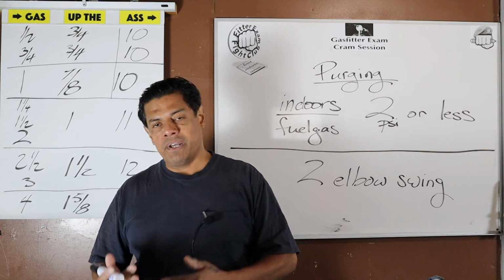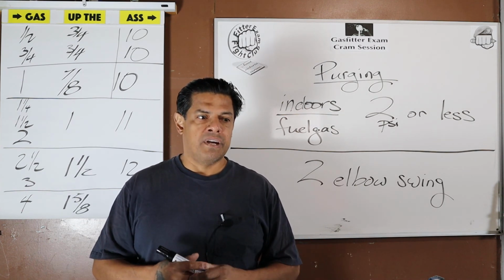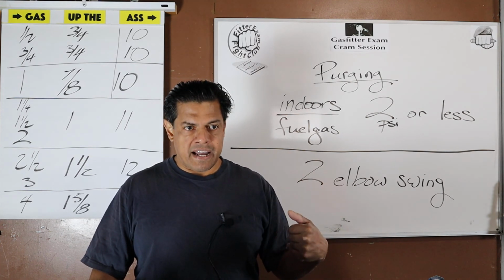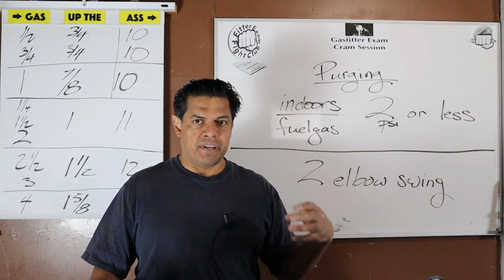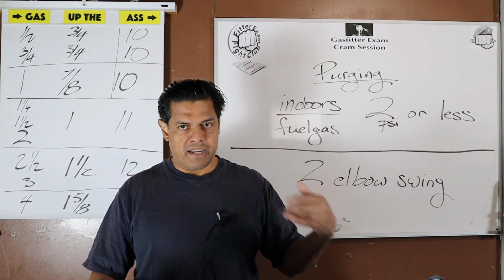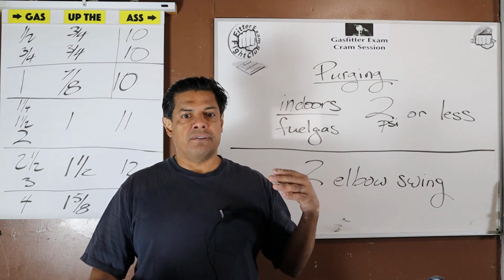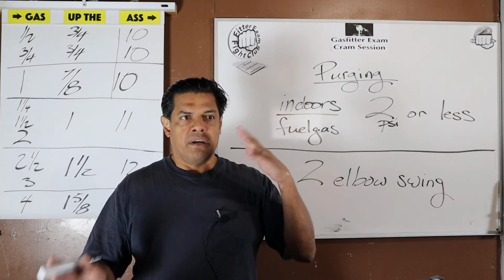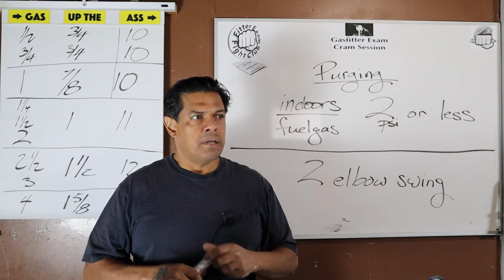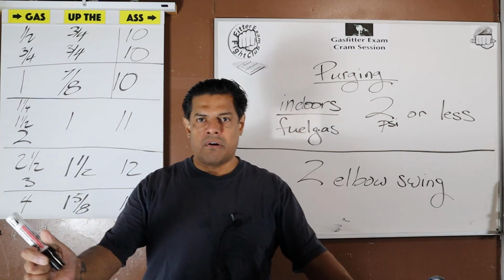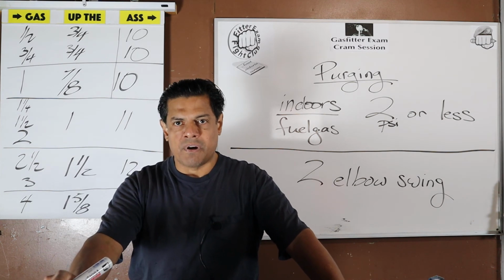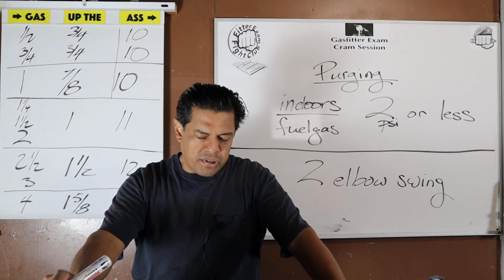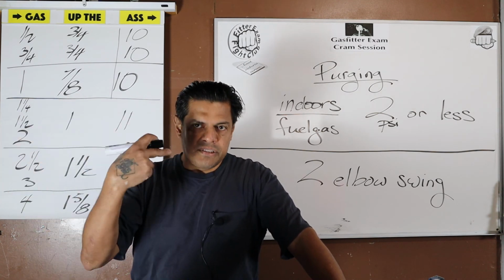But when it comes to the 2 elbow swing off the riser, if I'm in the wall, and to get out of the wall so that I have my appliance shutoff valve in the same room as the appliance, accessible, and just to get out of the wall, I went over and up and out. Those are 2 elbows. Did I not take my swing off? Did I not take a 2 elbow swing off the riser? I feel I'm done. Unfortunately, I'm not. I wish I was done. I'm not. It's going to stick out of the wall.